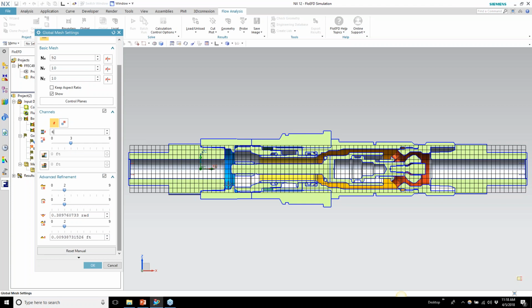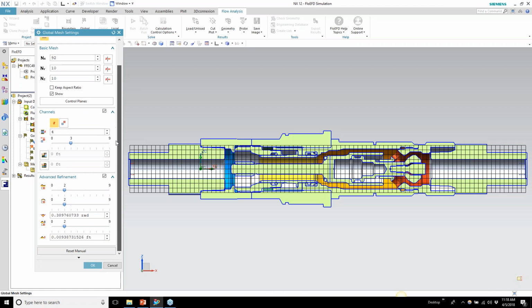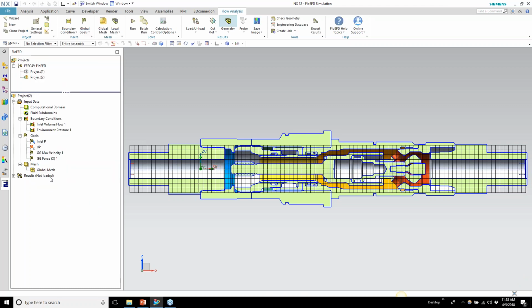So, for example, if there's a curvature on the solid, it essentially changes how the software is going to interact. So the higher the refinement, the more realistic the meshing will be, and how the software will analyze the project. However, it would take a little longer. So just checking our meshes here. It looks good. Oh, and we're going to hide the global mesh as well.